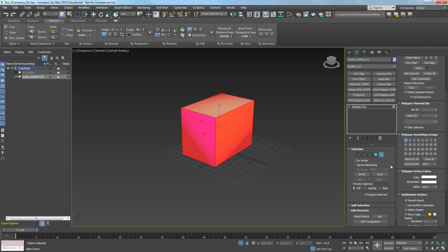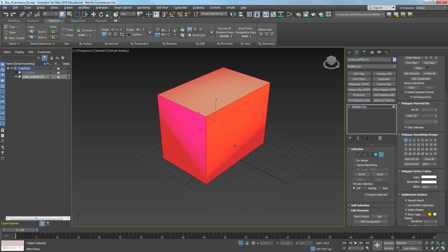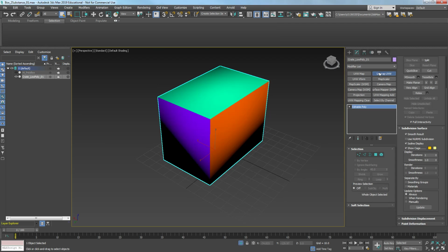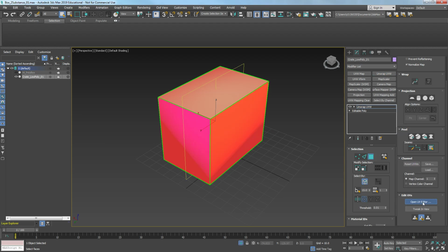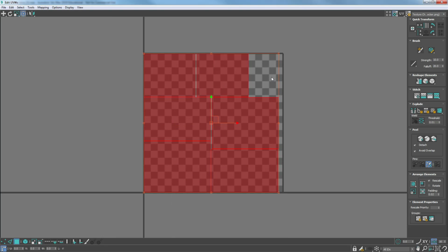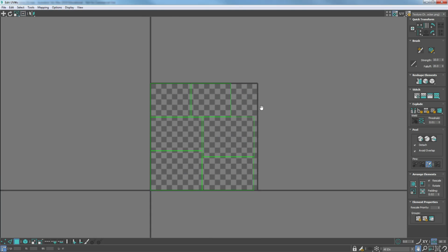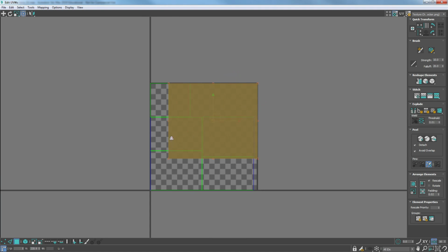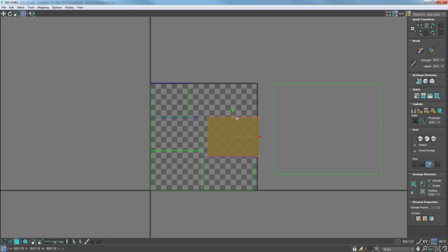Now it's going to render pretty ugly in 3ds Max, but that's okay. Next, I'm going to go to the Unwrap tool, and I'm going to basically scale up each one of my faces to where they occupy as much of the actual UV space as possible. I bet you anything, a nickel to a dime, there's probably an easy button for this, and I don't know what it is, so I'm just going to do it the manual way, but it's real simple.